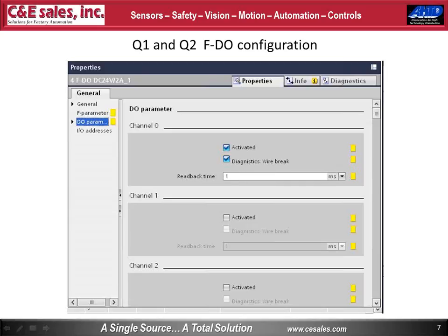What that means is that I have to have an actuator connected to this activated output, and there's a bit pattern test that can be done on fail-safe outputs, which means that the output is very rapidly cycled on and off. There are 2 parts of that. A dark test is executed about every 15 minutes when the I/O module is working correctly.